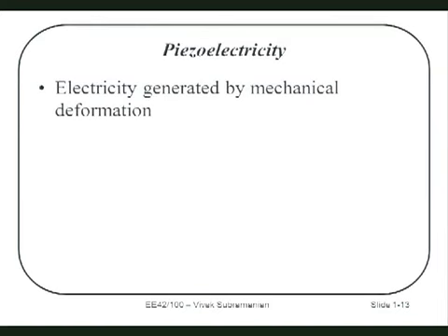Okay, so the HP printers actually use what's called thermal print. It's a bubble jet, which means they heat up the ink inside the canister, and it boils right around the heating point and generates a bubble, and that pushes the drop out. So instead of using mechanical deformation, they heat it to cause it to come out. There are two competing technologies. They have advantages and disadvantages, but it is what it is.